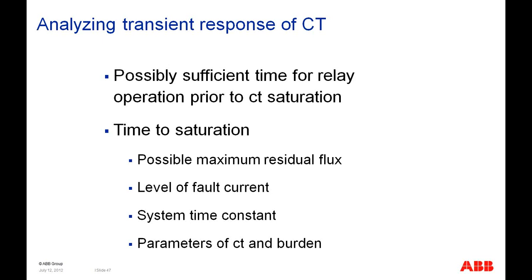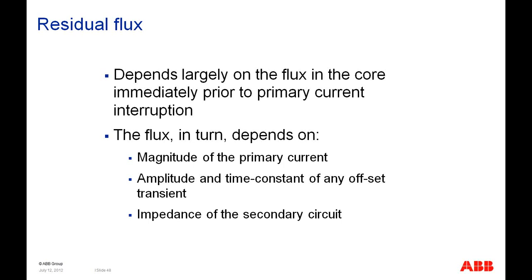given situation. So the time to saturation is made up of several factors. One is the maximum residual flux that we have in the current transformer, the level of fault current that we're applying to the current transformer, the system time constants, and the parameters of the CT and the burden. So the residual flux depends on the type of core and what's happening on the current transformer prior to